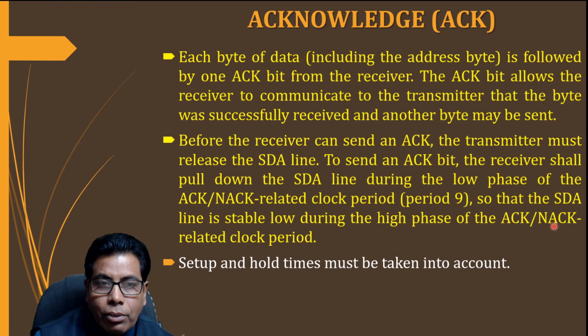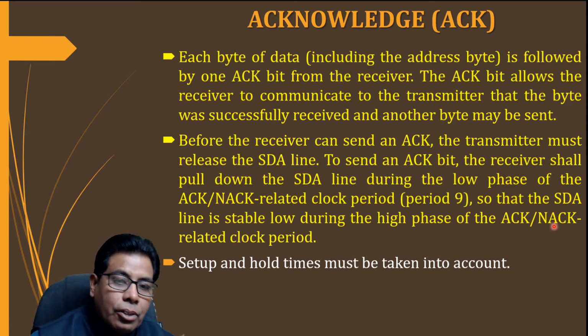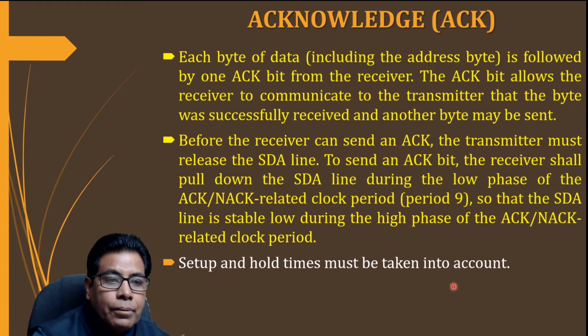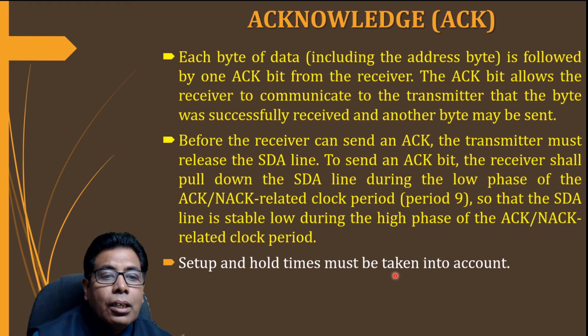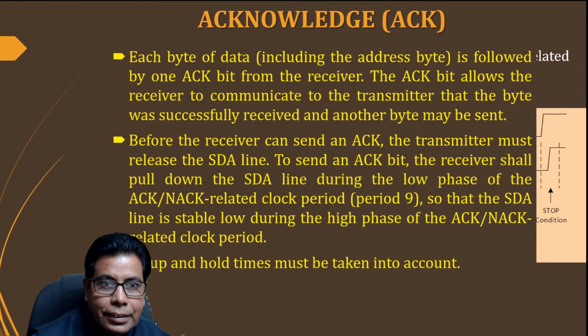So the acknowledge pulse will be low, whereas the not acknowledge pulse will be high. Setup and hold times must be taken into account in order to validate the acknowledgement. So it is just during the period 9. If it is low, then we call it ACK, and if it is high, it is the not acknowledgement.